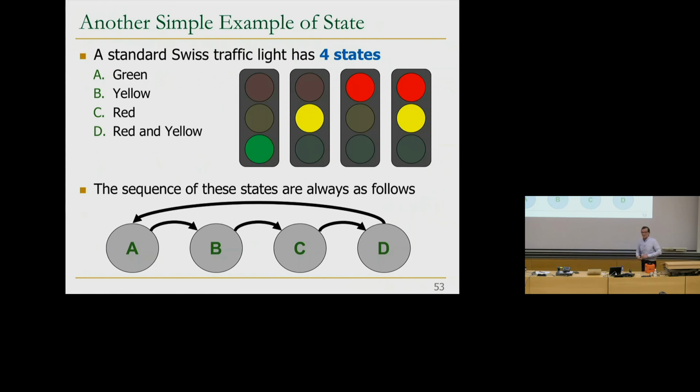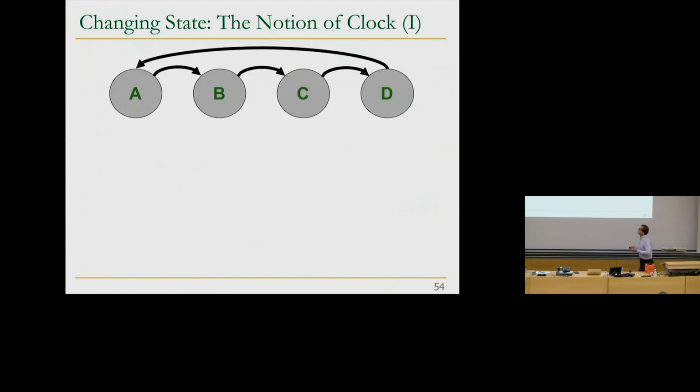Okay. So the point is there needs to be something that's input over here that transitions these things. It's not an external input in this case, although we're going to make this traffic light smart later on, or somewhat smart later on, that takes external inputs. Here, there should be an internal input that says, okay, it's time to transition, right? You can think of this as a timer. And to be able to implement a timer, we need something else in the system. And that's the notion of a clock, basically.